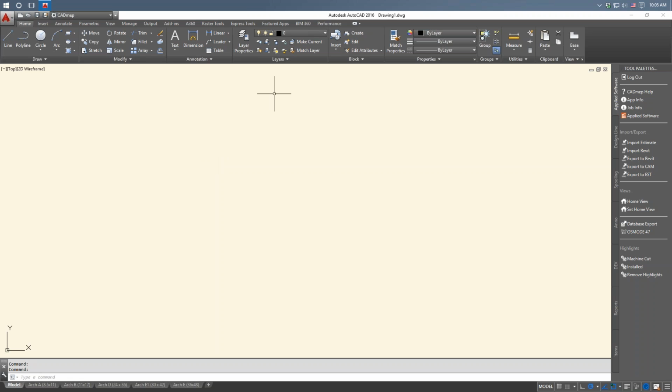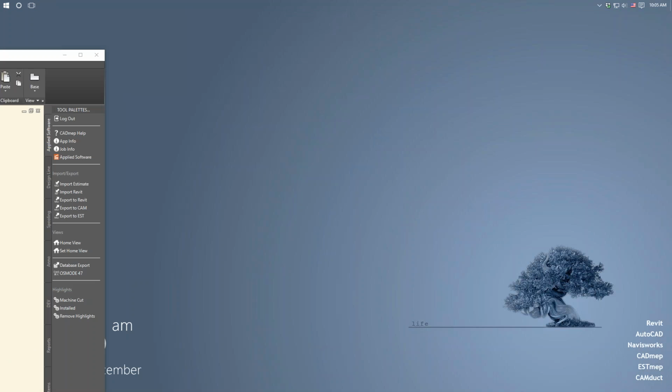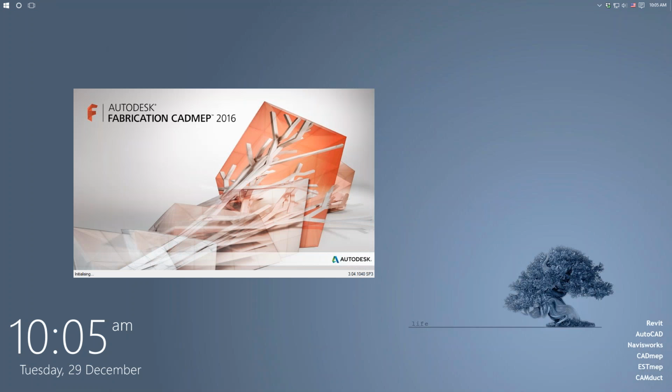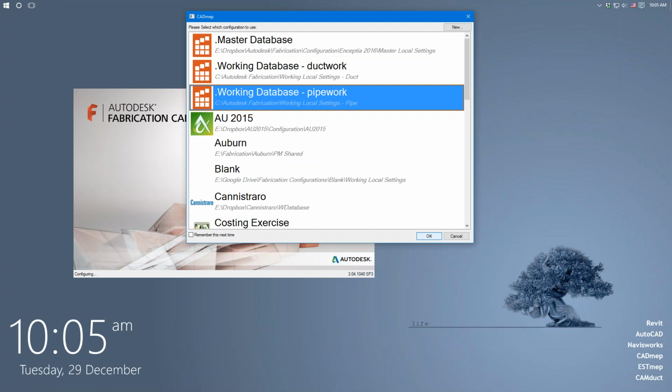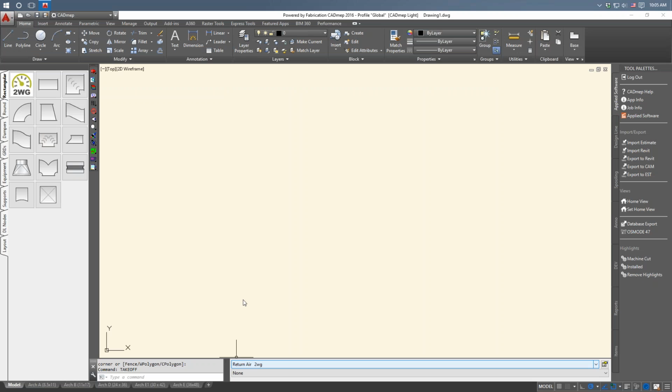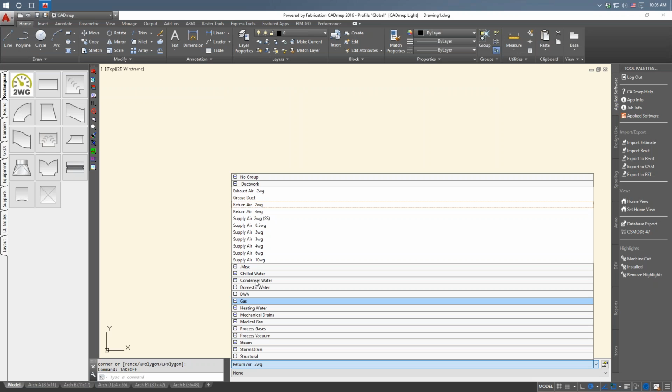Another question, not on the slice tool, but as you're getting restarted: what is the recommended way to add slope to pipe? Was the positioner command to do that, or is there another command that you would recommend? After it's been placed, I'm guessing. All right. We got running here again. Yeah, after it's been placed. Okay. Positioner is probably the best way to do that.